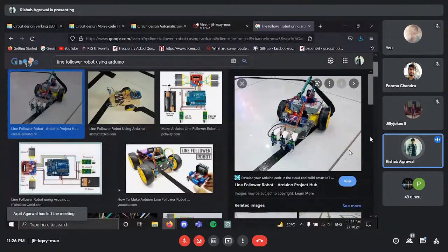So the car is continuously moving forward according to what the Python code is giving the serial monitor of the Arduino. And you're just changing the speeds of the motors in the Arduino code based on what the LDRs are sensing. So that way the left and the right turning part is automatically taken care of because of the differences in the speed of the motors. The only thing that PySerial is doing is sending the forward message to the Arduino. That's all.